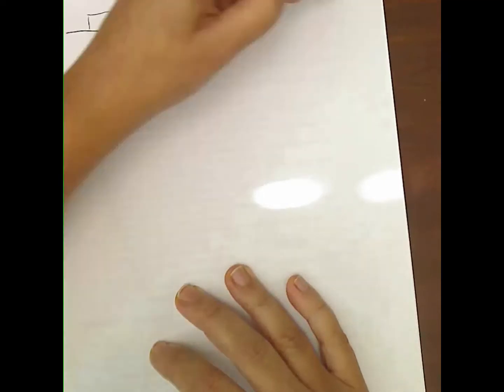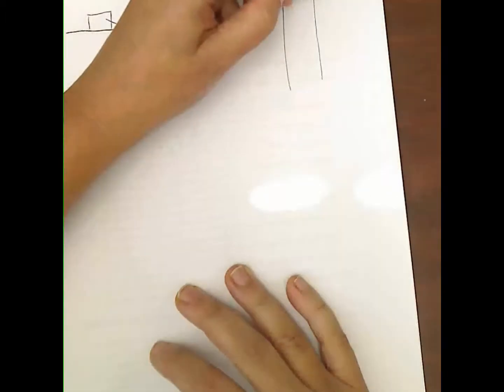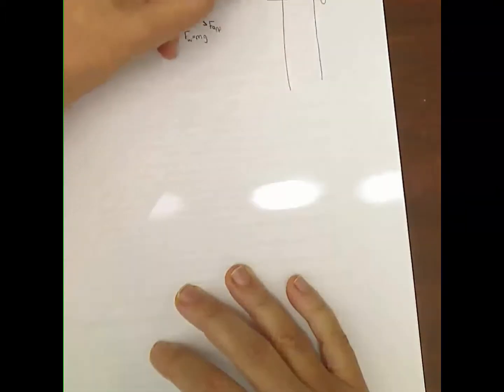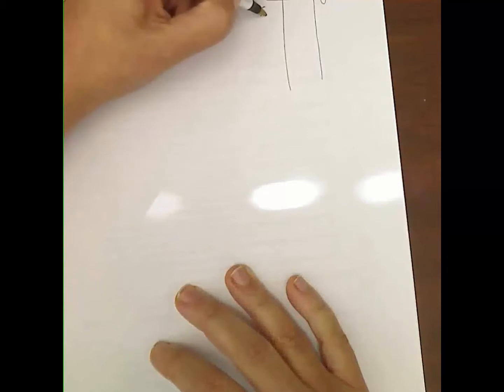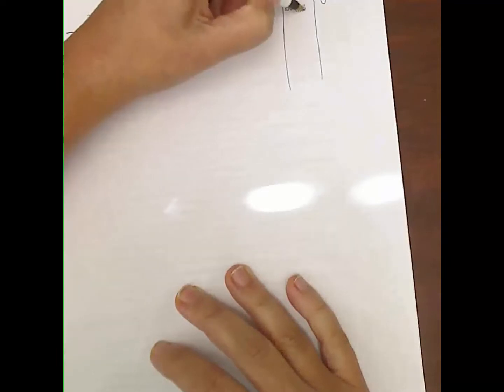So make up our table, just like we did before. Put in our 4 things. Alright, so applied force is 100 newtons. And now it's going to have a y component that's negative because it's downwards, and an x component that's across. So I've got 100, and again this side, the x side, is adjacent to the angle, so it's cos 30.